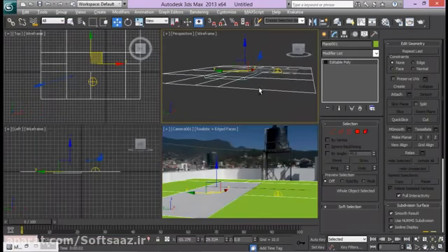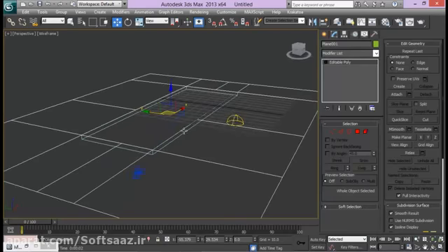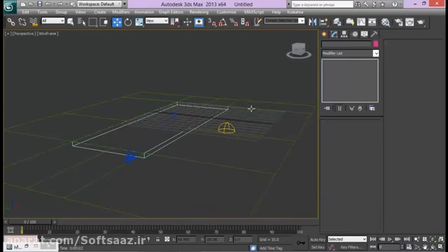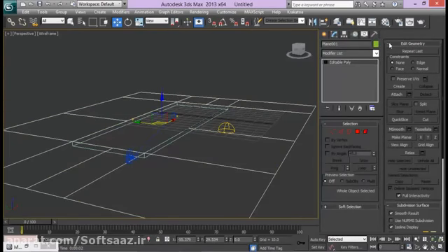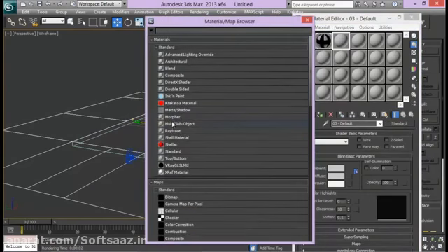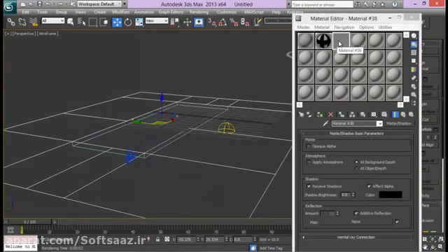We won't be rendering this green plane, but it will still hide the depth of this box so that it will be seen as if it has been integrated into our scene. So let's go to the material editor and load up a material called matte shadow. This will only render shadows on any object where it has been applied.